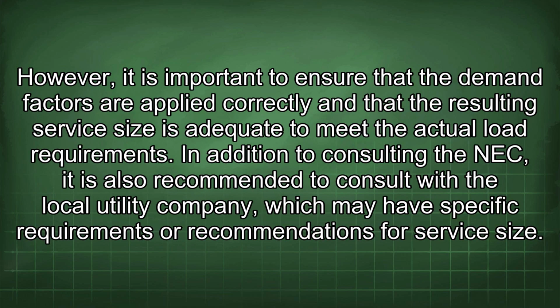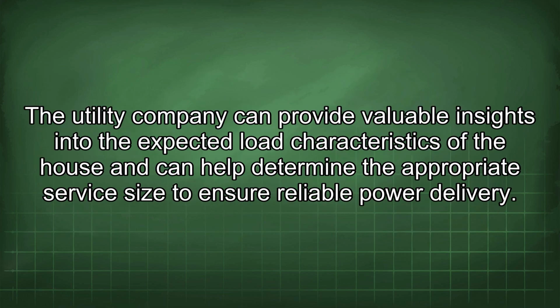However, it is important to ensure that the demand factors are applied correctly and that the resulting service size is adequate to meet the actual load requirements. In addition to consulting the NEC, it is also recommended to consult with the local utility company, which may have specific requirements or recommendations for service size. The utility company can provide valuable insights into the expected load characteristics of the house and can help determine the appropriate service size to ensure reliable power delivery.